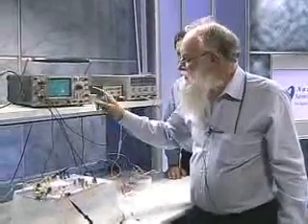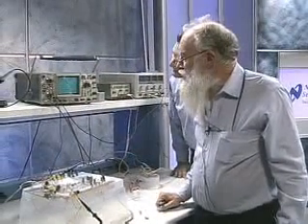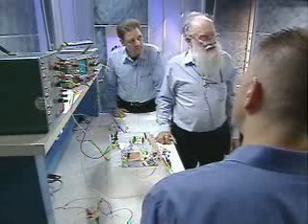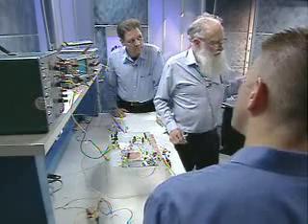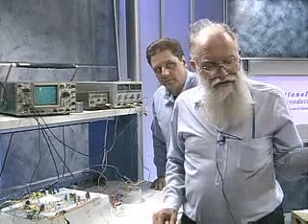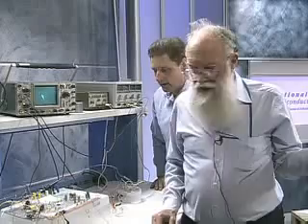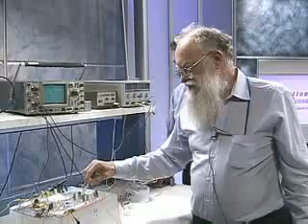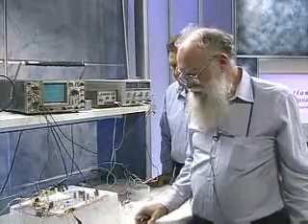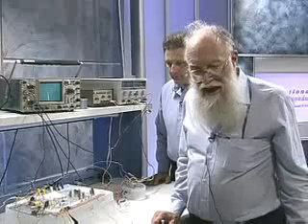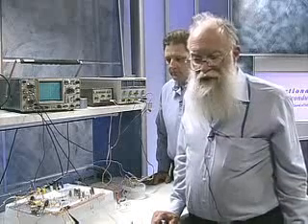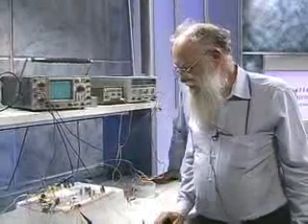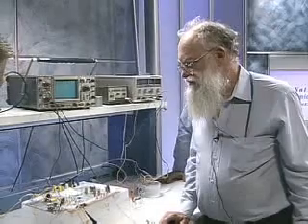We can move that around to detect small errors at about 3 hertz, because if you're doing it at 300 hertz, you're measuring inductance. At 3 hertz, you're measuring resistance. That's what we're trying to evaluate. Are these 2 resistors good? Yes. Do we have more resistors? Yeah, I got some 5 milliohm resistors, but I haven't got them here right now. We can write that up and have it on the site later.